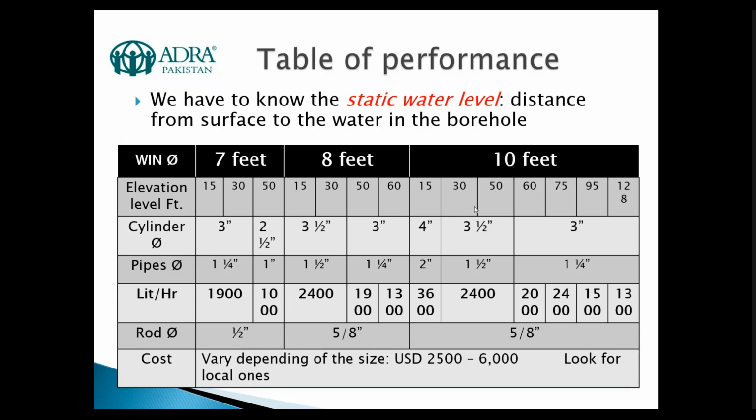Especially we need to know the performance, comparing dams and other devices with the device that we are using, the windmill. And you have different sizes, used according to the depth of the water that you can take. We have fans with propeller diameters of 7 feet, 8 feet, 10 feet, those are the most common in the market. In our case, in Pakistan, we are using this 10 feet because the depth of the water is very, very high.